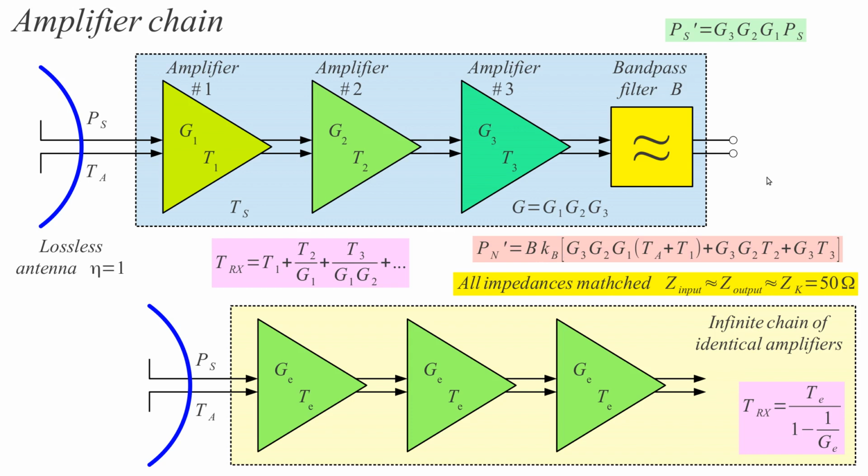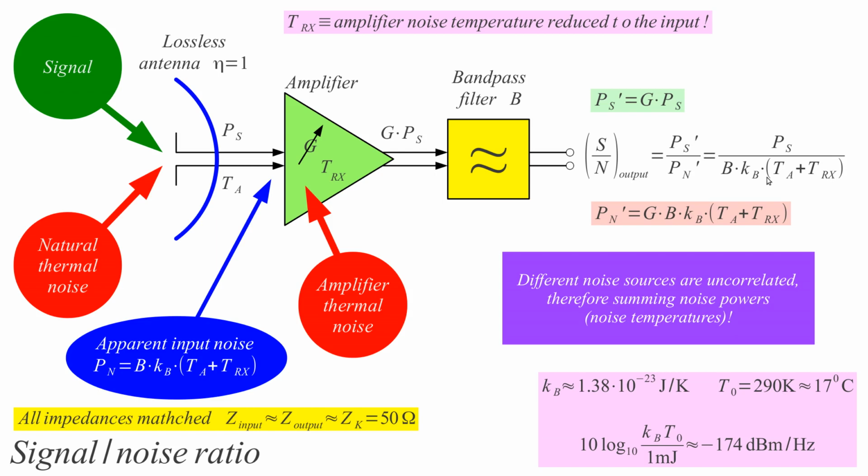All these calculations here always involve linear units. So we have linear units for the signal to noise ratio, for the powers, for the gains. We do not have any logarithmic units here except for this Boltzmann spectral noise density of thermal power in dBm per hertz. This is the only logarithmic unit we ever encounter here. But not all people think this way.